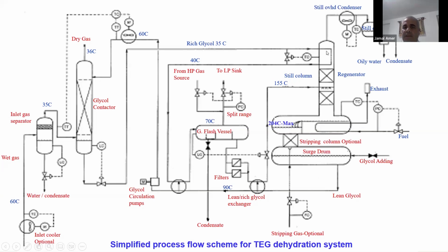Here also this reflux, as I told, gives us good function by cooling the vapor which is released here. Here this is the reboiler, and we have the still column. So we have some vapor coming through the still to the vent. When the vapor goes around this reflux coil, it will lose its temperature, and we call it reflux.